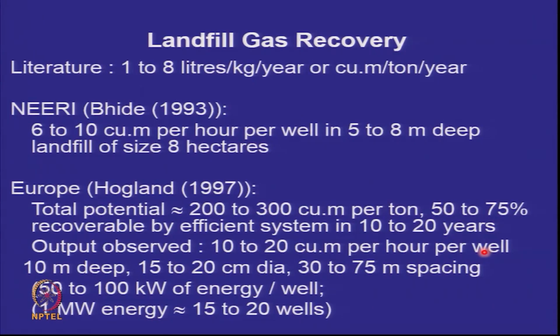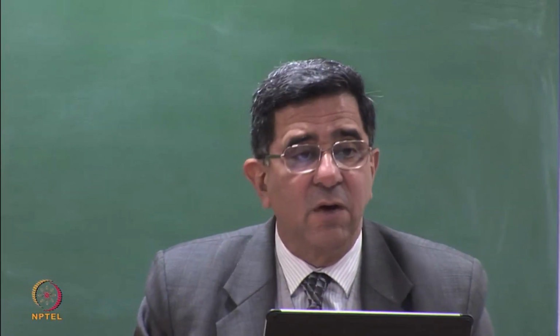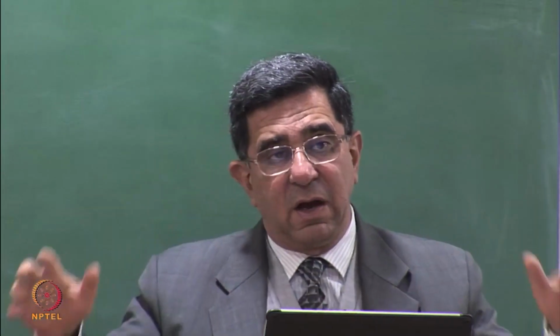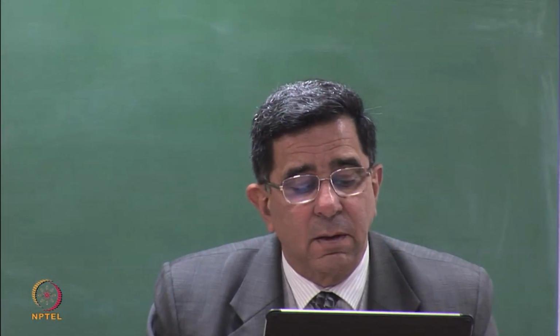But you remember, this is a more efficient system. Here, the landfill that we are talking of is a well-designed landfill with a liner and a cover. Whereas here we are talking of an open waste dump. If you have an open waste dump and you put a well in it, this is the kind of gas production rate that you get. If you have a well-designed landfill with a cover and a liner, you will get a higher output.